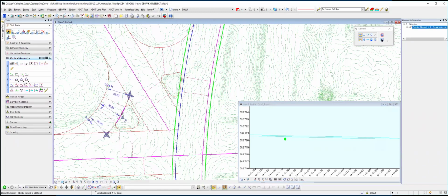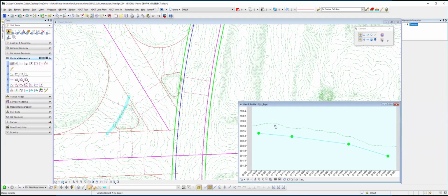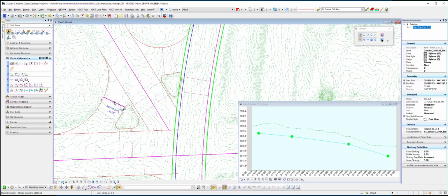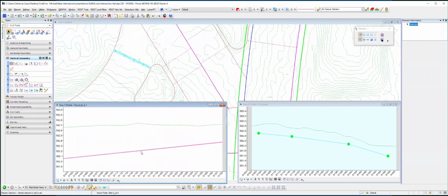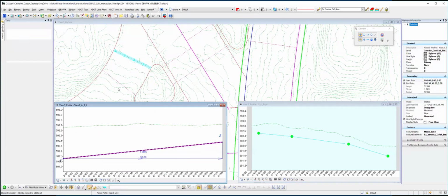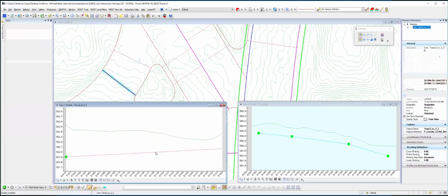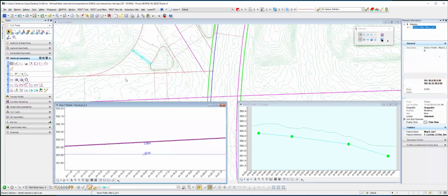The other thing I want to talk about vertically is the two different approaches for these particular islands, and it's going to depend on what you're running into. In this case, I actually put in set slopes for each one of these control lines here. In this one, I wanted 1% here, and at this line, I wanted it still draining toward the island, but less, as I'm trying to blend into the pavement section over here.